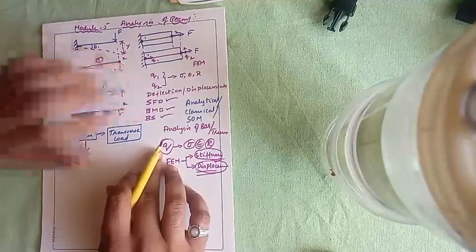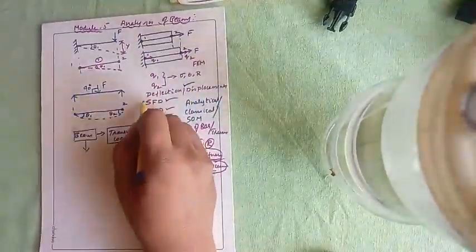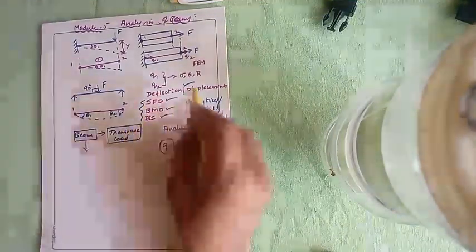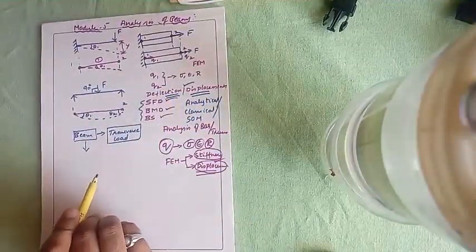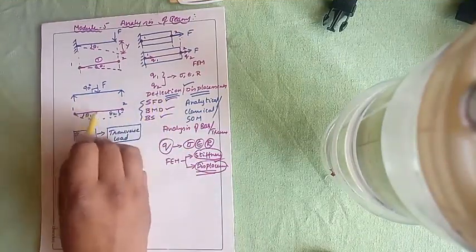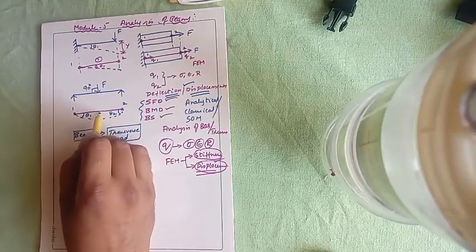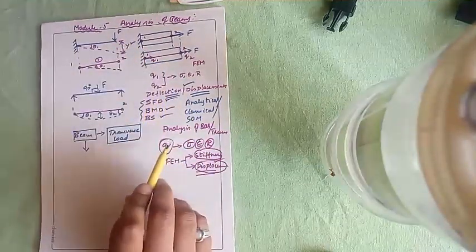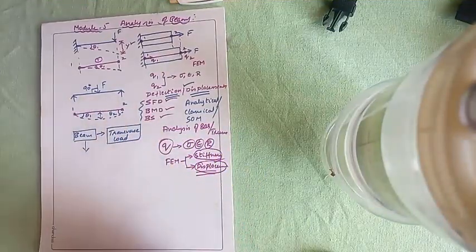Later will be our bending stresses. We are going to find out all these unknowns, that might be shear force diagram, bending moment diagram or bending stress, by first finding out the nodal displacements or the deflection. Generally when it comes to a beam, we never call it displacement, we call it deflection. Look at this, this is the initial position. When the load acts, it will be deflected from its mean position. Whatever y I am showing will generally be called deflection. But when we solve problems with the help of the finite element method, we call it nodal displacements.